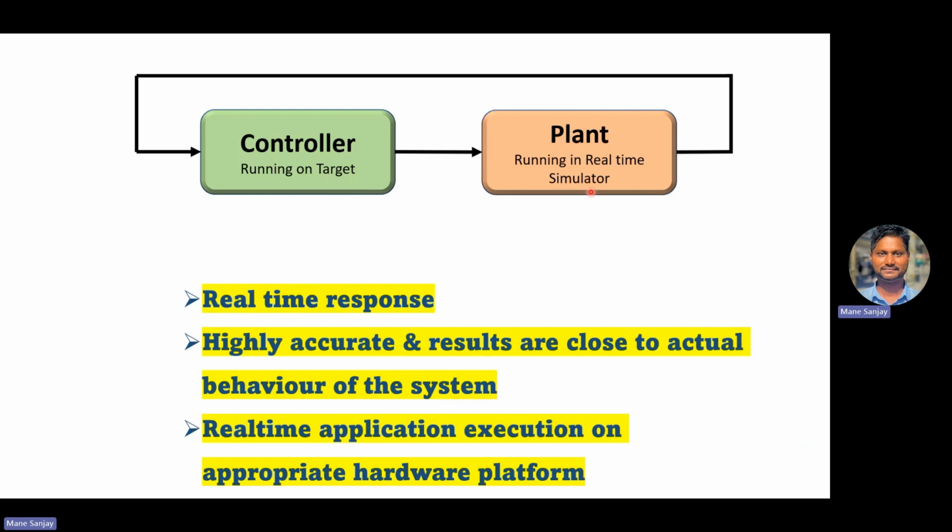I'm going to talk more in detail about this hardware-in-loop simulation because in it, not only the real-time simulator and the ECU come into the picture, there are different parts of the hardware-in-loop simulation like breakout box, then fault insertion unit, then load box. So many major components, major blocks, play an important role in the HIL system. I'm going to cover that in more detail in my next knowledge sharing session in the next video. But today I am restricting myself to just talking about the overview of the HIL.